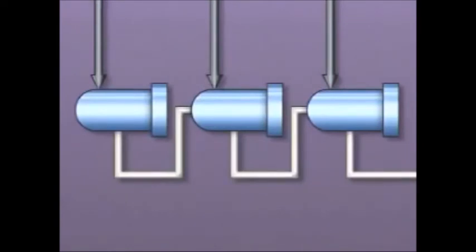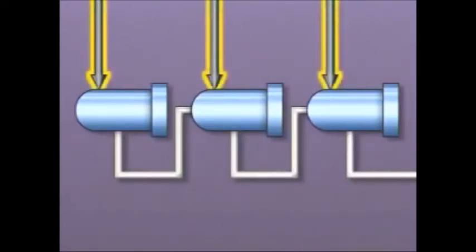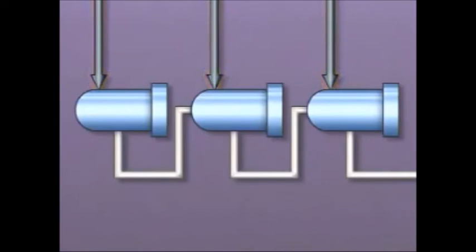Typically, to recover the maximum amount of heat from the extraction steam, a train of heaters uses a cascading drain system. In each heater in the train, drips are subcooled by the transfer of heat to the feed water in the heater's drain cooler section. This helps keep the drips from flashing to steam in the drain line. The flow of drips moves from the highest pressure heater to the lower pressure heaters.